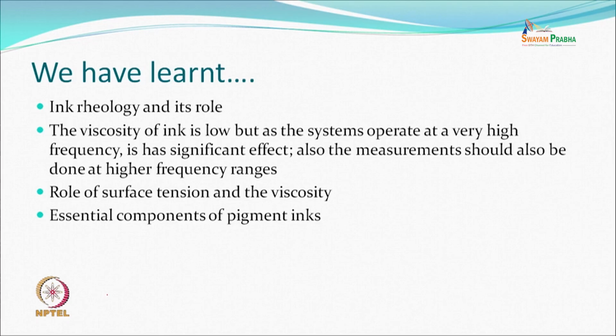The rheological measurement should therefore also be done with instruments which operate at a high frequency, not at a very low frequency, which does not simulate what is happening in the jet. Role of surface tension and the viscosity is what we understood, and also we learnt, as far as the pigment inks are concerned, what are the essential components.